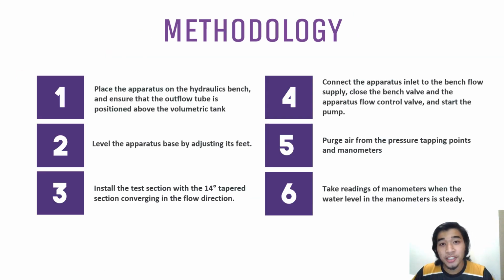So let's go to the methodology of this experiment. These are the steps on how to conduct this experiment. The first one is to place the apparatus on the hydraulic bench and ensure that the outflow tube is positioned above the volumetric tank. The second one is to level the apparatus base by adjusting its feet.